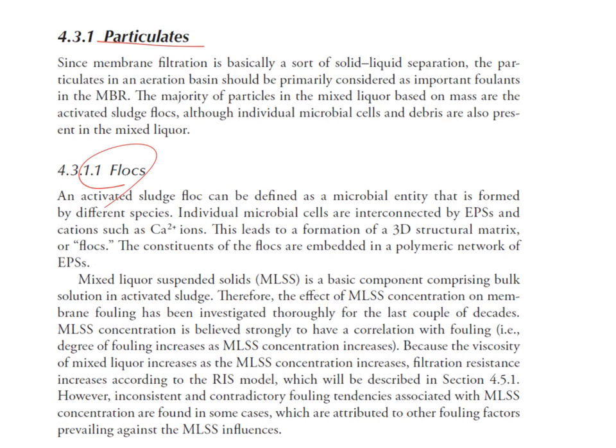Individual microbial cells are interconnected by EPS and cations such as calcium ions, and this leads to the formation of a 3D structural matrix or floc, and the constituents of the floc are embedded into a polymeric network of EPS.